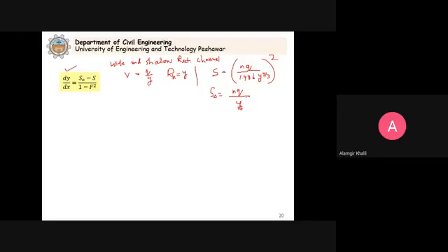Clear? Now in this case, this is also Y naught to the power 5 by 3, and from here this is Y to the power 5 by 3. And just to be unit consistent, we write down 1.486, and this whole squared.